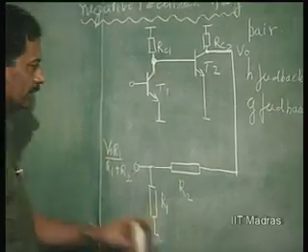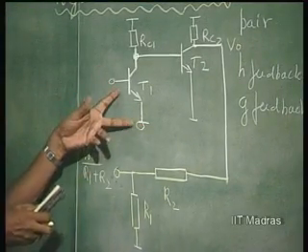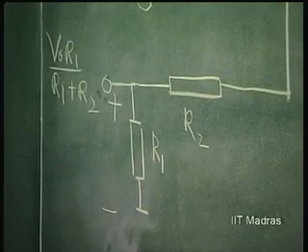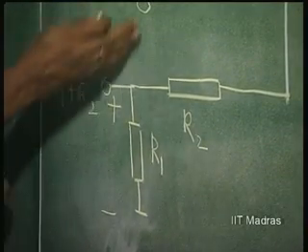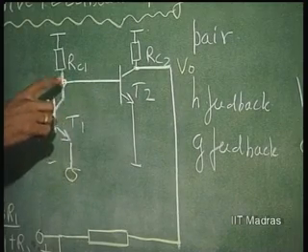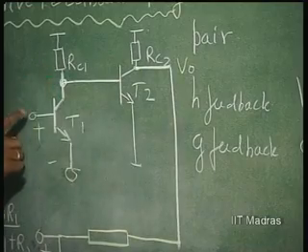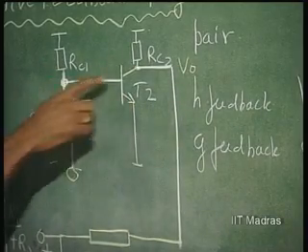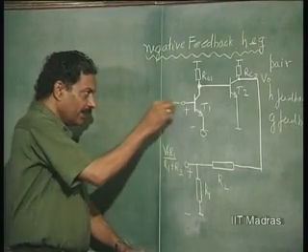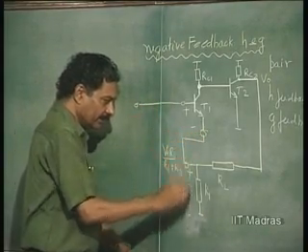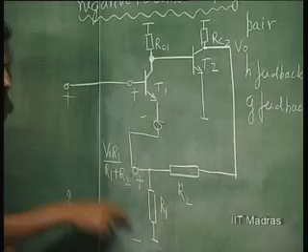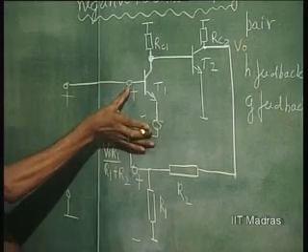That is going to be put in series with the original input. The original input of the amplifier is this, and this is the feedback voltage. So, we are going to lift this and put it in series. From here to here the phase shift is 180 degrees. From here to here again the phase shift is 180 degrees, and therefore the output and input voltages are in phase. If I now apply this feedback voltage in series with the input, it will be opposing the input voltage. That is why it is negative feedback.